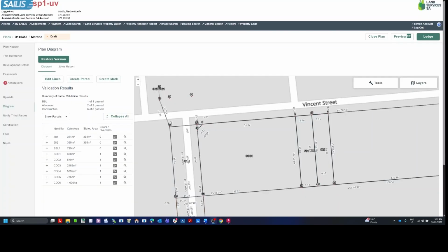Some additional drafting practices to help with data processing for your closures reports. Draft a single diagram in model space with one set of parcels and one set of parcel identifiers to prevent duplicate parcels in the closures reports. Ensure that the MGA zone in the title block matches the coordinates that the geometry of the diagram has been drafted in model space.